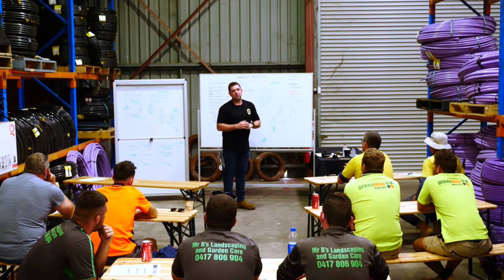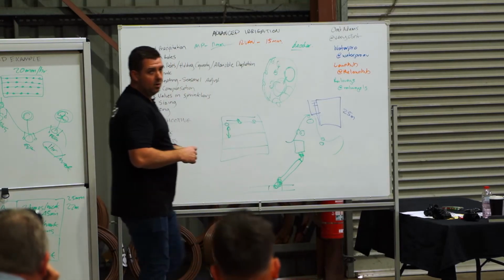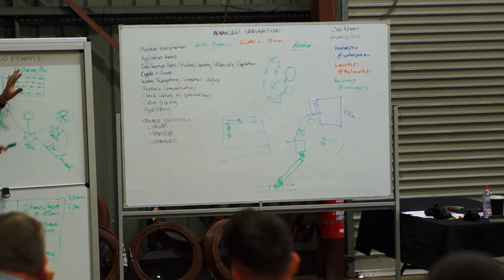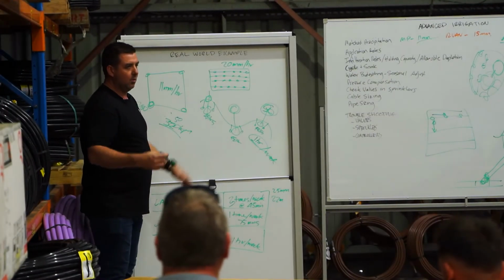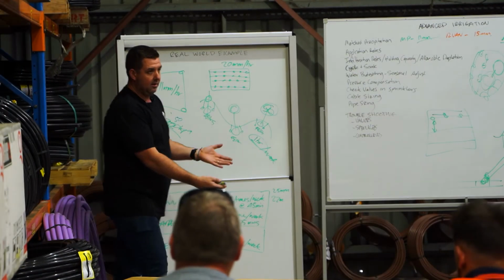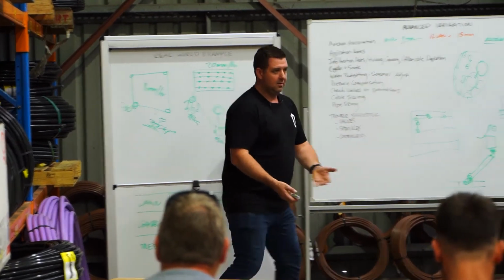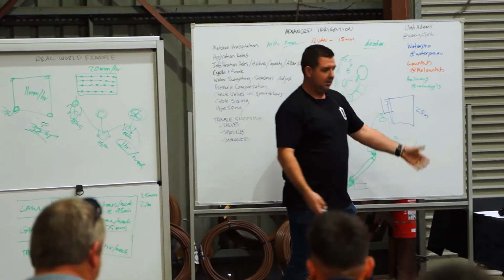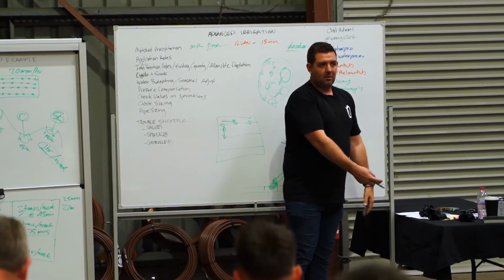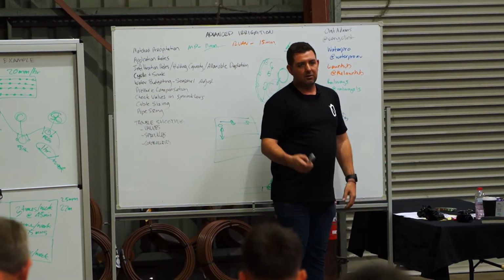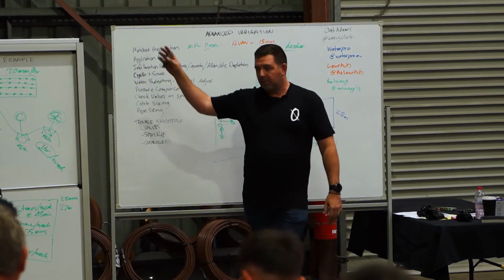It gives you further security so that if you finish the whole job, especially commercially, and it doesn't work and they're like, well, what happened? You're like, well, here's a video of us doing a pressure versus flow test before we started. Here's photos of all the pipes in the ground. You can see the sprinklers. Something's changed, and they're like, no, it hasn't. And you've just got this evidence that you prepared it all.